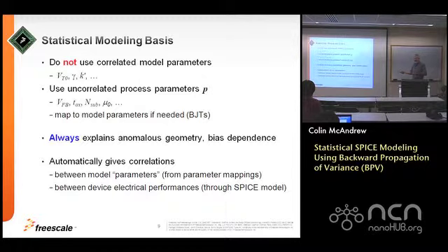So there's not a complete independence here, but there's a little bit of hiding some things under the hood. In practice, it turns out to work fine, but you really should use these uncorrelated parameters. For MOSFETs, that's generally reasonable. The tricky one is bipolars, which I won't cover here, which aren't constructed from physical mappings from process parameters, so you have to add those.